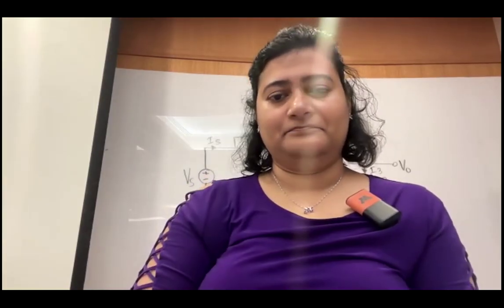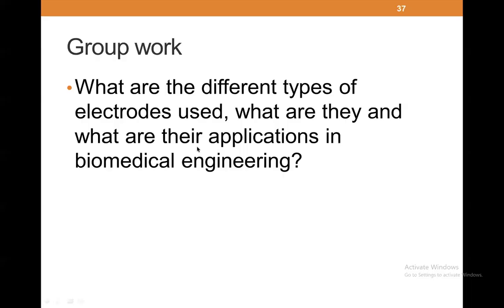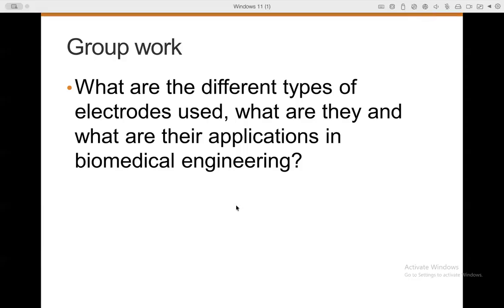So we chose loading electrodes, and basically what they are is a standard metal plate electrode, but they're recessed into a cavity of usually gel. By doing that, any sort of motion or artifact that's caused by the subject would be absorbed by the gel instead of the electrode, so that the signal will remain clear, and then that can be used for a number of things.